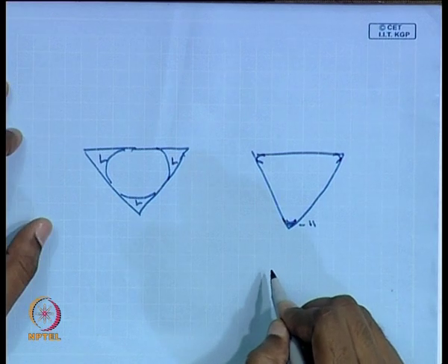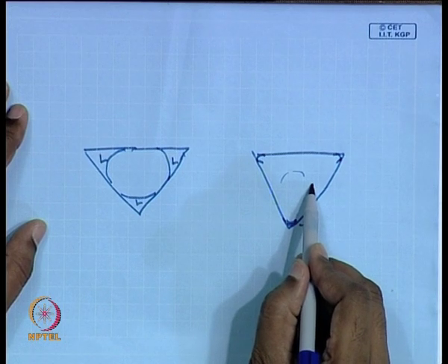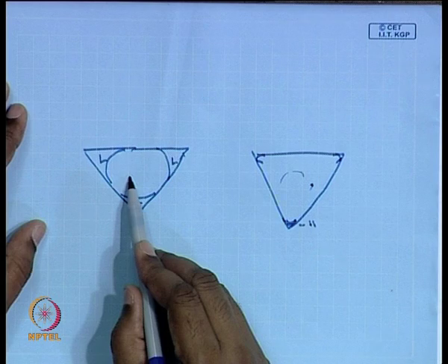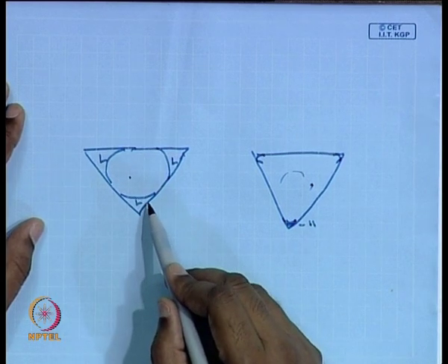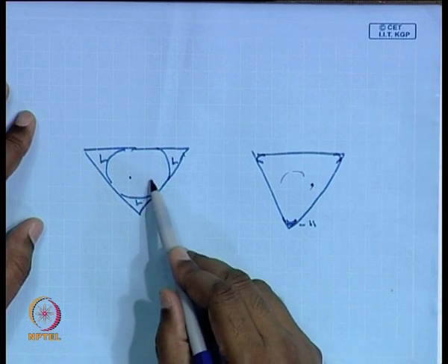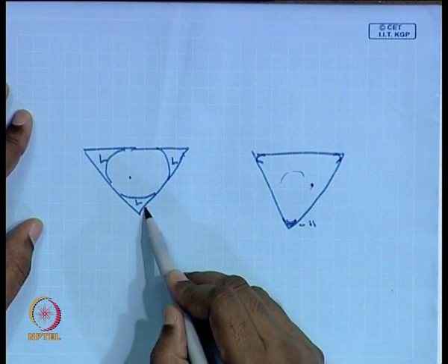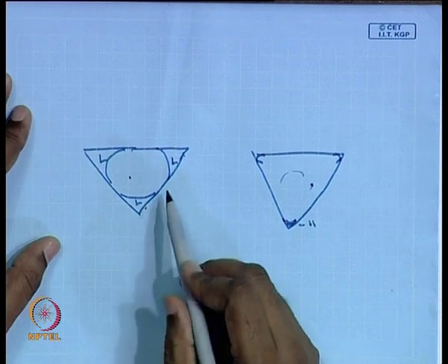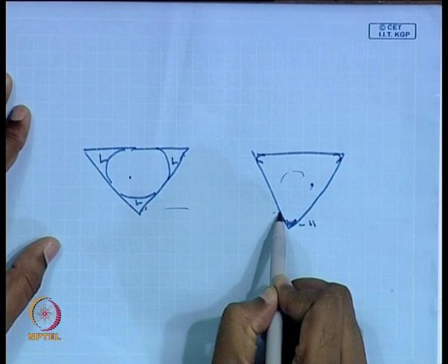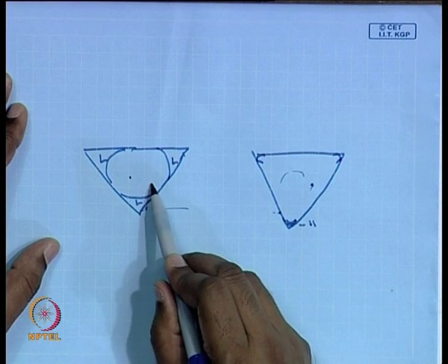But what happens to the vapor? The vapor is going to be generated in this region, which will flow through the core towards the cold side, and if you consider the amount of evaporation and the difference in densities between the liquid and the vapor, the velocity with which the vapor has to flow will be very large compared to the liquid velocity. Is that part clear? A small amount of liquid coming towards the hot side and getting evaporated will generate a large volume of vapor,